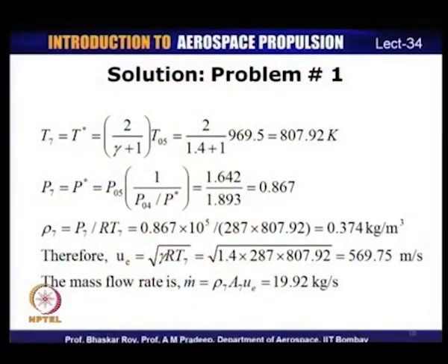And so, how do you find the critical pressure, temperature and density? We have to first find these critical parameters, because that is now the exit condition, and then accordingly we can find the exit velocity and therefore, the thrust and fuel consumption and so on. So, let us first find the critical pressure, and we already have the ratios with us, and from those ratios we can easily find it. The critical pressure, temperature and density need to be determined to calculate the nozzle exit conditions.